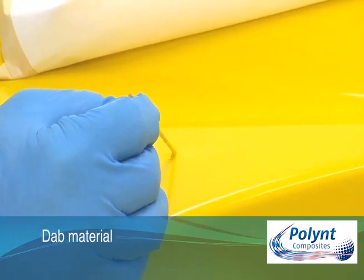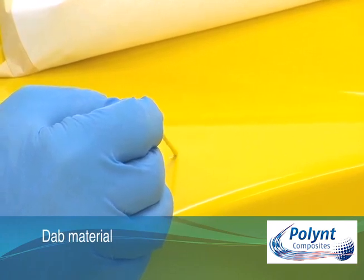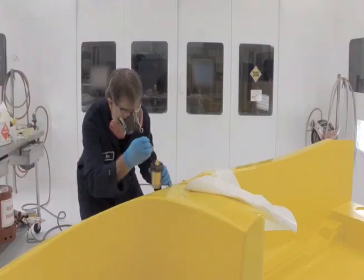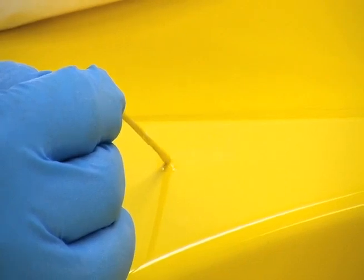For spot patching, use a knife or spatula to dab the catalysed gel coat mixture onto the damaged area. Slightly overfill the area, including the area around and above to allow for shrinkage. Puncture and eliminate any air bubbles that may be trapped in the gel coat.